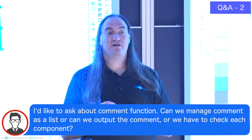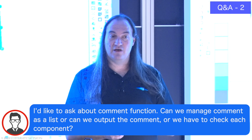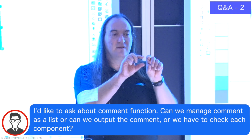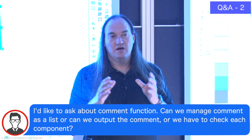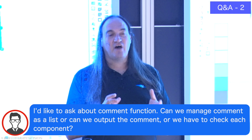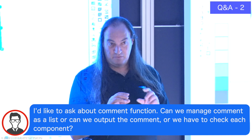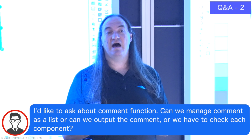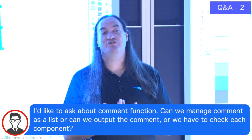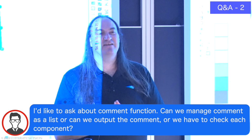Alternatively, many of the comments are written to the CC file. So if you have a comment for a heat load, there'll be a comment block right before the logic for that heat load that says, this is heat load such and such, or conductor such and such, or contactor such and such. So sometimes the information might be available in the CC file, which is a text file. Other times it may not, and you would use the API if you wanted to try to extract that documentation for a report or something like that. So it can be done, but it's not clean.